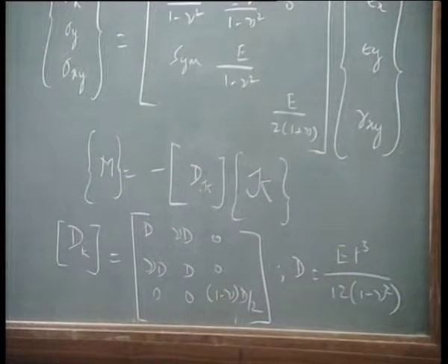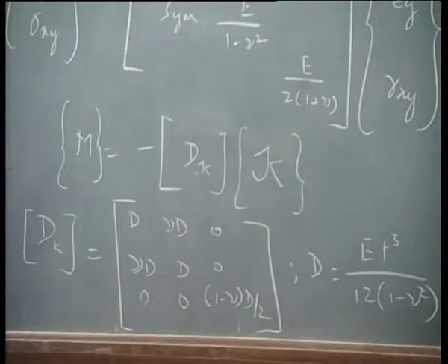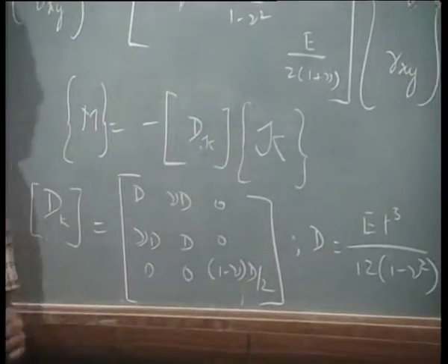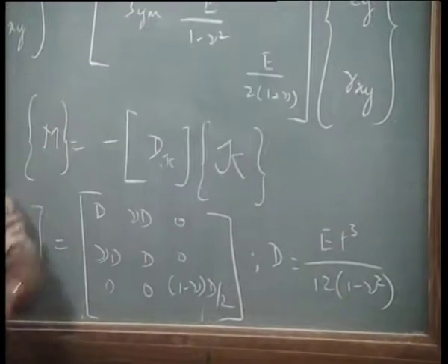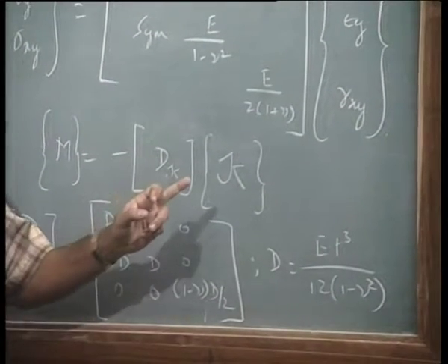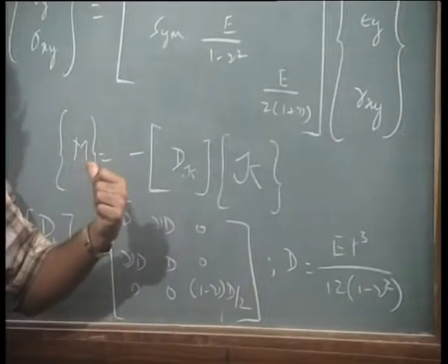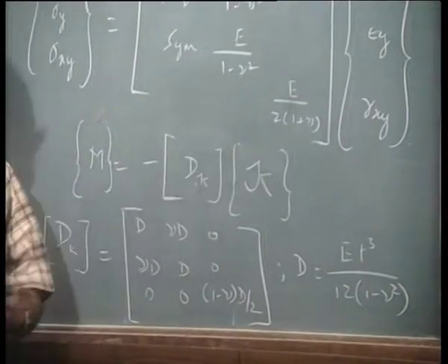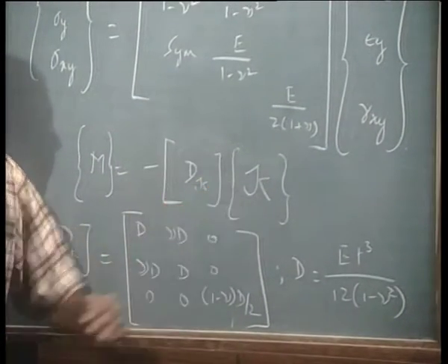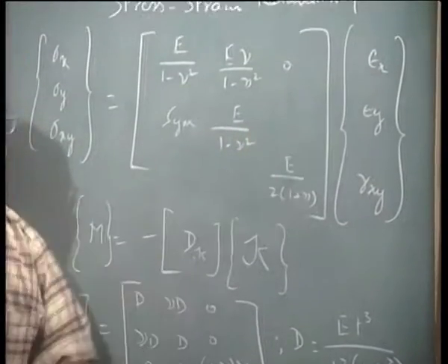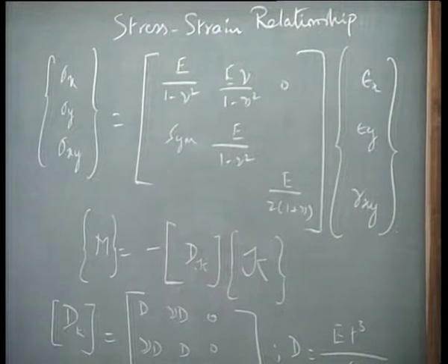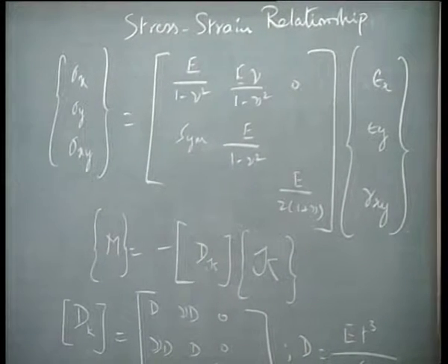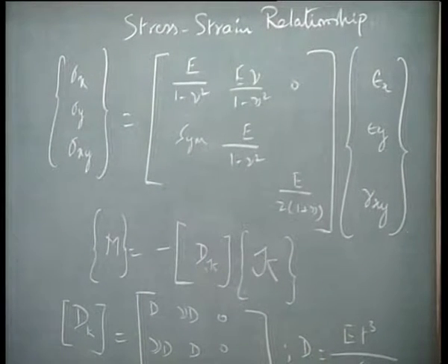Now, it is customary to write this equation in terms of moments and curvature. From where do you get the curvature? By writing down the expression for epsilon x from the displacements u with the familiar equations which we know, we get curvatures. In other words, when I substitute u, we would get terms like w comma xx, or dou square w by dou x squared, and so on.